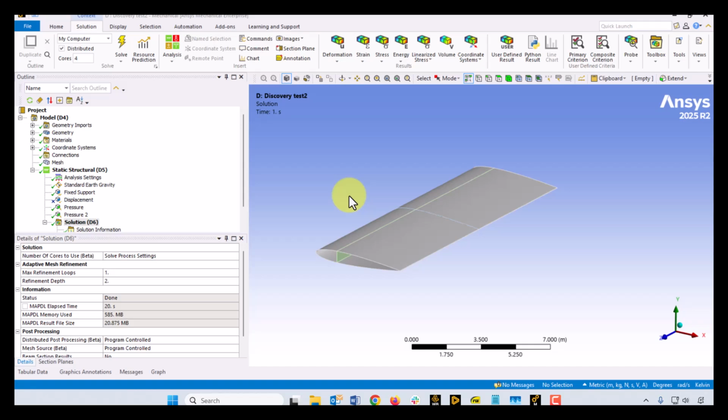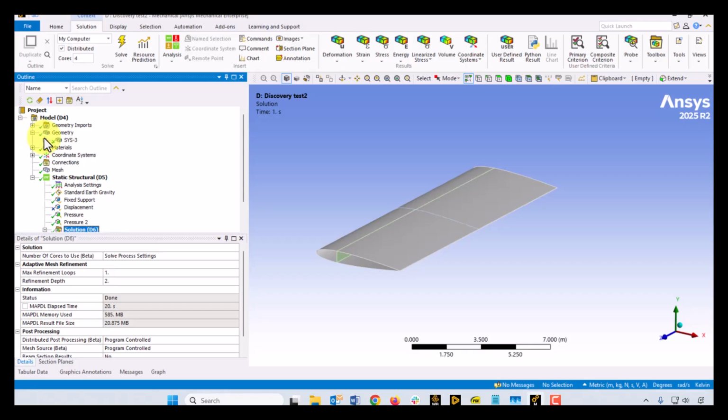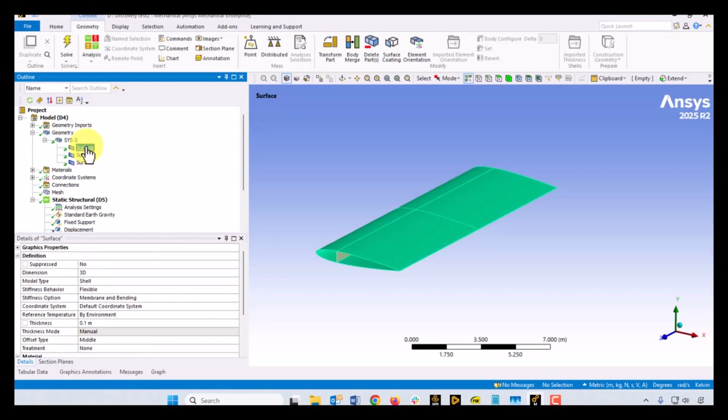In this video, I'm going to show you the setup in Mechanical for your inertial wing design. When you import the geometry into ANSYS Mechanical, you should see you have one body with subparts because we have shared the topology. So if I click on surface, that's the skin surface, and again, we have only the mid surfaces here, and then we have the rib and we have the spar, and you can rename it, and you